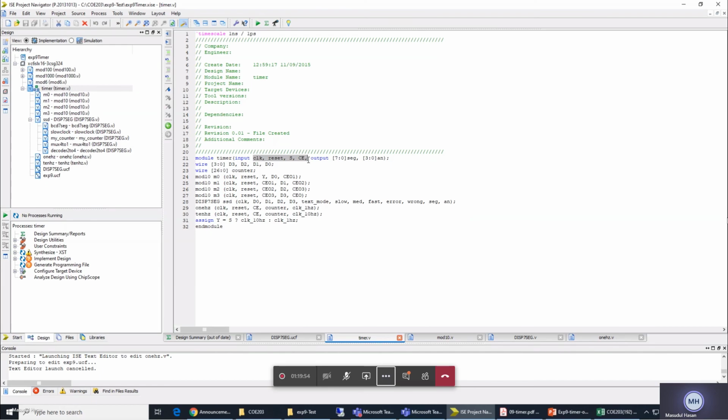Go to project, clean up project files, right? Project, then clean up project file. It will delete all of these unwanted ones. Click OK. And now see here. Again, go there, project, clean up project file. No file is there.